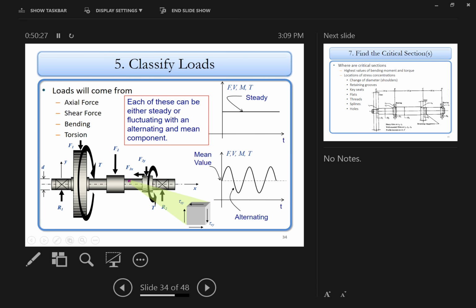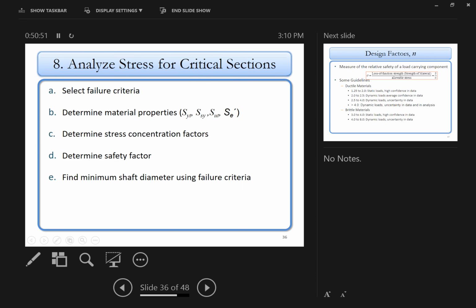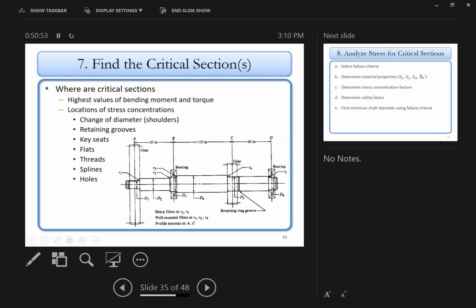That's what we call the combined loading condition, combining different types of loadings together. In the previous lecture, what did we use? We used the von Mises equation to calculate the equivalent sigma_a' and sigma_m'. Those are some of the equations here, and I'll show you.